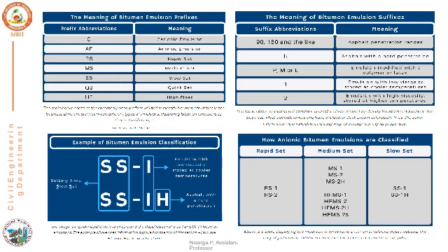And if we use any suffixes or abbreviations like 90, 150, H, P, M, L, 1 or 2: H stands for asphalt with hard penetration, and P for emulsion modified with polymer latex. Number 1, if it is there, means emulsion with low viscosity stored at cool temperature. If we have the suffix 2, it indicates emulsion with high viscosity stored at high temperature. And similar to that, we can classify the anionic bituminous emulsion. So here RS1, RS2: rapid setting 1, rapid setting 2. If it is RS1, it indicates rapid setting, and 1 indicates emulsion with low viscosity stored at cool temperature.